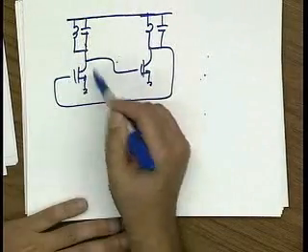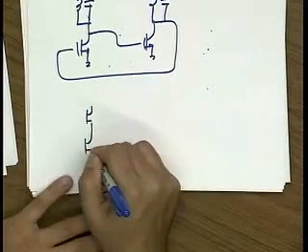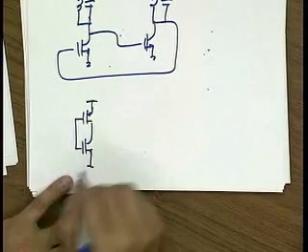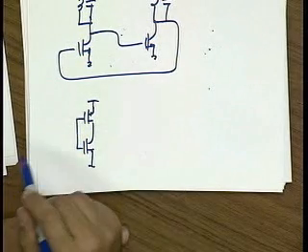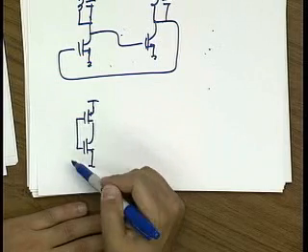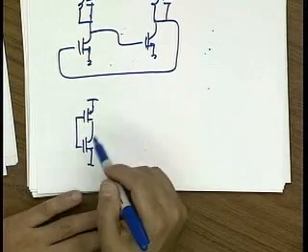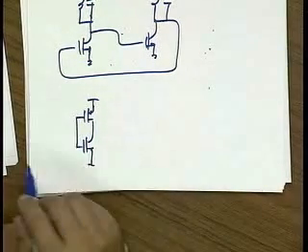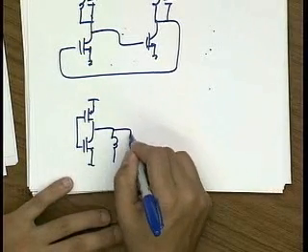Well, what's another inverting amplifier? Well, I could also use something like a CMOS amplifier. The nice thing about a CMOS amplifier is that it's also inverting, but as you guys saw in the first midterm, the GM of this guy adds to the GM of this guy. So it's like having two transistors in parallel, but sharing the same current. So that means that for a given current budget, I can get more loop gain out of this, or vice versa. For a fixed loop gain, I can get less current.